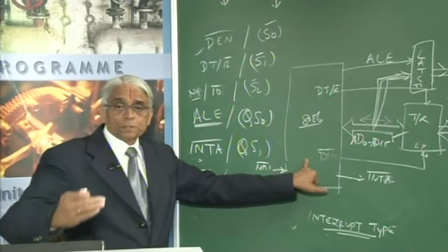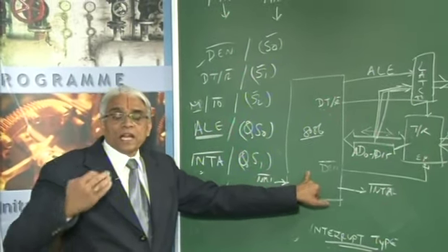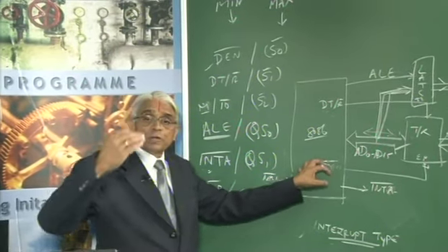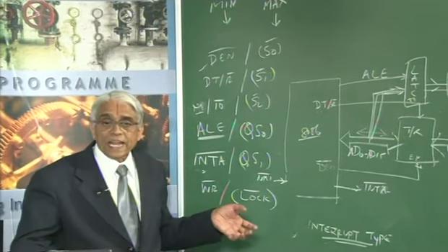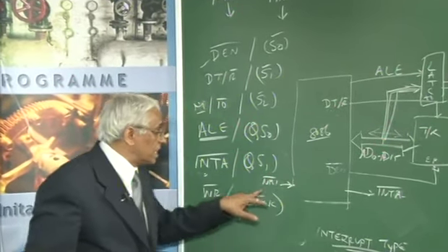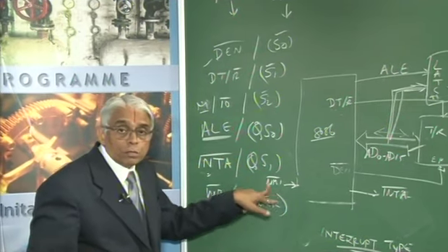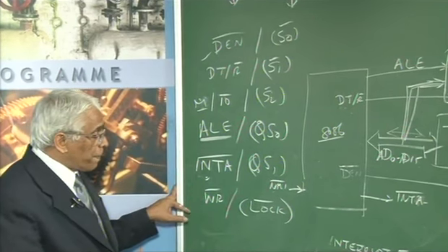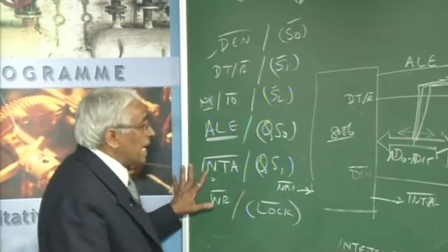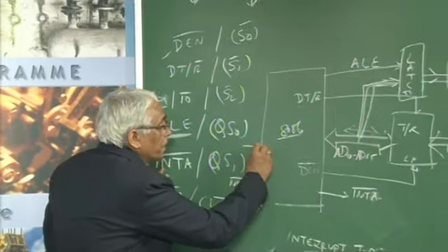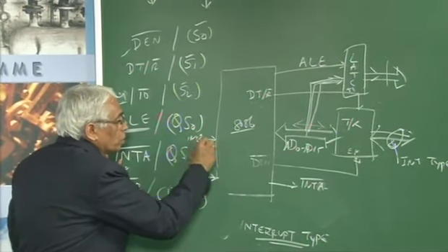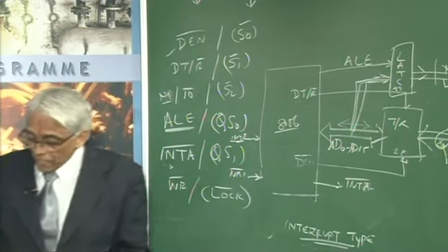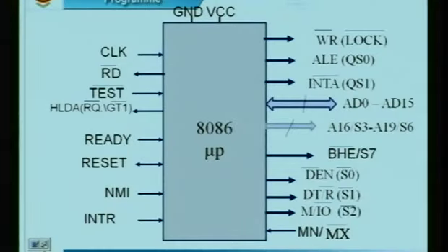There should be an interrupt service routine that has been written, which enables the processor to execute a set of instructions to set things right or to send an alarm. So, this is not maskable. The INTR pin can be masked, whereas the non-maskable interrupt pin is a pin which cannot be masked.